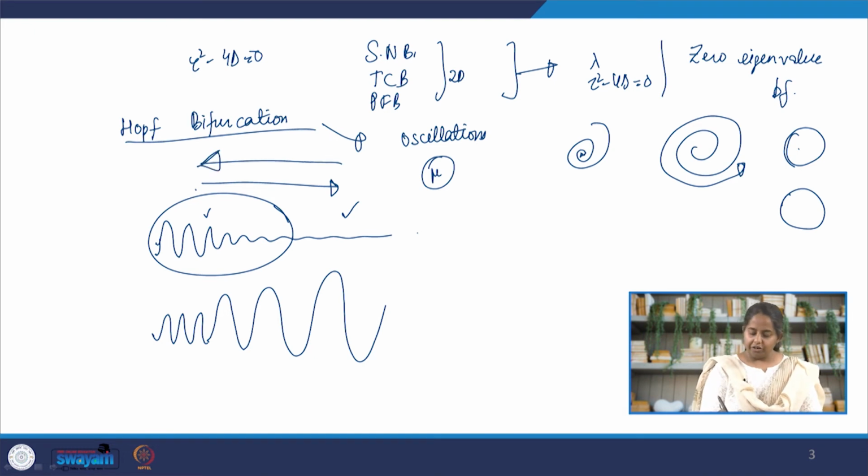Either way, what we are noticing is that if we draw our eigenvalues, with the imaginary portion on the y axis and the real portion on the x axis, when we have complex conjugates for our eigenvalue, when there is oscillation happening, we have a non-zero imaginary part, and since it is dying out, in the example that I am looking at, the oscillations are reducing in amplitude.